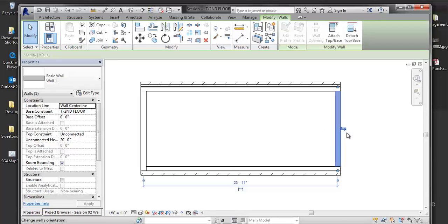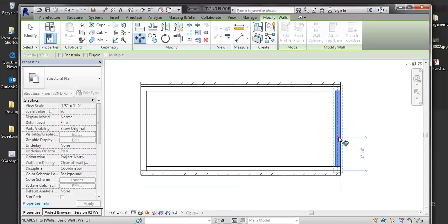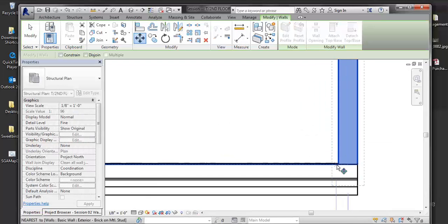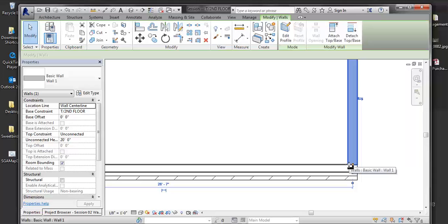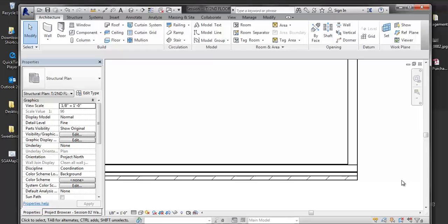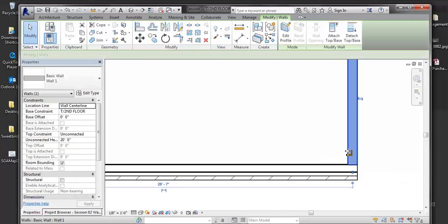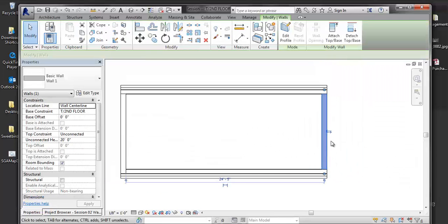Yeah, if I wanted to move this particular element without using the dimension string, it's better to say MV and then do it. You can do MV and then actually move it from a reference line or a reference point. So I'm saying, okay, I want to move this wall a specific distance this way, not by growing the whole assembly of that rectangle as well. Can you type everything? Yeah. So there's a button right down here that's press and drag. Oh, good. Get rid of that. Yeah, exactly.